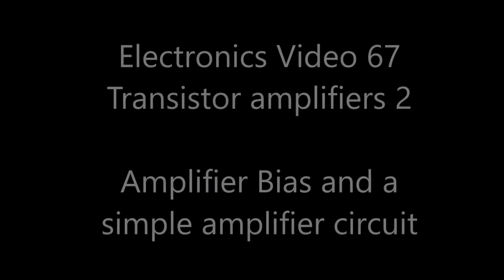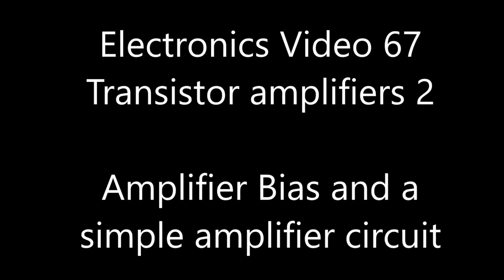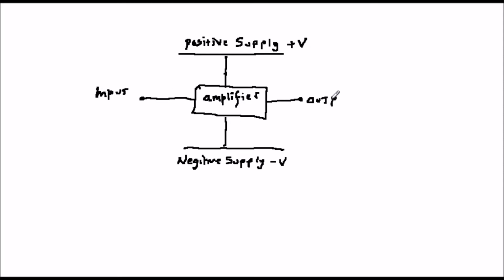The last video illustrated a problem common to all amplifiers, not just to transistor ones. Because the output voltage Vout of the amplifier was sitting at a supply voltage VCC with no signal, it couldn't increase further when a signal was applied. The answer to this problem is to arrange in some manner for the output signal to sit halfway in between the positive and negative power supplies when no input is present.